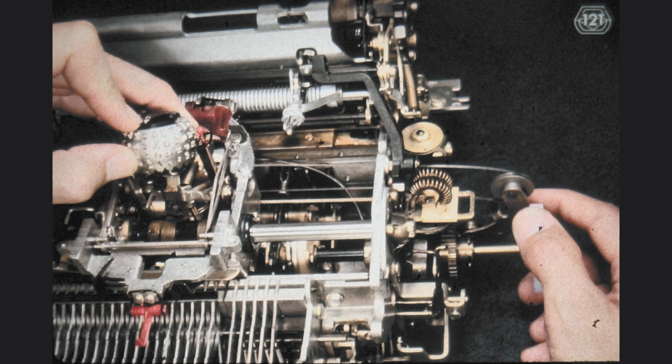If you have to turn the element slightly more or less than 3.5 turns in order to get the rotate pulley to position the hookup point for the rotate tape towards the front of the machine, think nothing of it. We can always make it up by rotating the spring cage, as explained earlier. Once we have half-cycled a character and lock the element into position, we are ready to install the rotate tape.